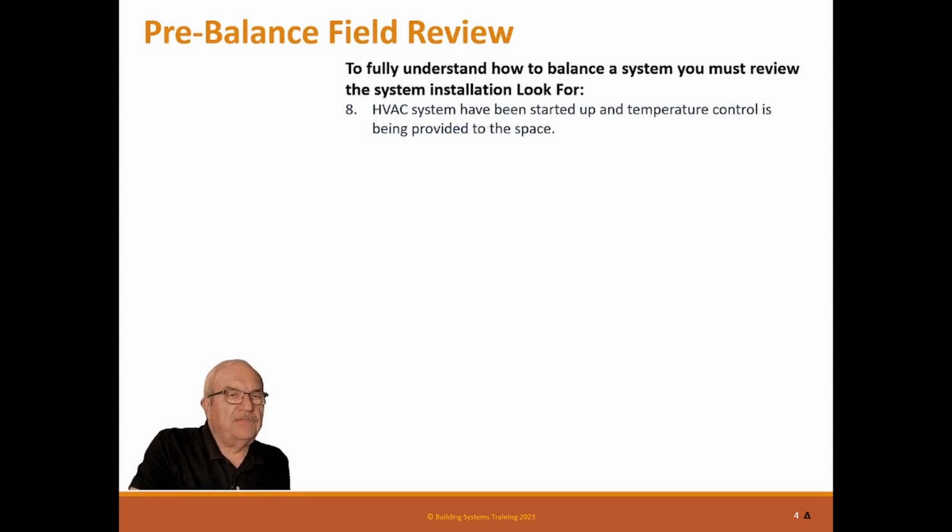HVAC systems have been started up and temperature control is being provided to the space. Has the mechanical contractor actually started everything up and is it running? Unfortunately, sometimes some mechanical contractors think startup means turn it on. It actually doesn't. There's a lot of things they need to do, and those need to be done before we get there.